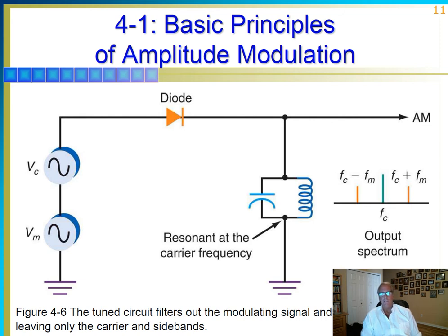And this works. I mean, this is actually a practical circuit. Now this over here, you can't really put two signal generators, so to speak, in series with one another. You use a summing circuit here, which you can use an op-amp for, or perhaps some resistor summing in front of a transistor circuit or something like that. So this is sort of a semi-practical, semi-block-diagram-ish diagram.